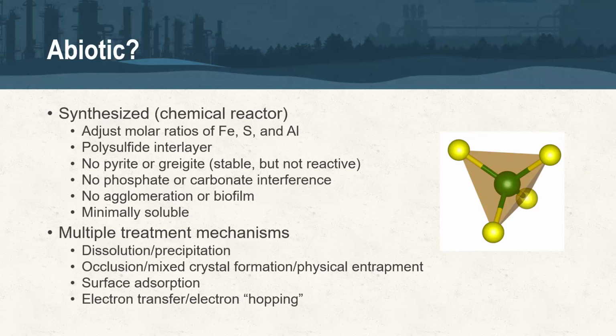But once you go through that process and you identify the most appropriate type of iron sulfide, you can work on loadings through your bench testing. And that's really where you start to look at the different treatment and removal mechanisms you're dealing with, right? Especially if you have a mixed metal site, it may not be as simple as using a 2-to-1 molar ratio of iron to sulfur. It could be completely flipped around. It might be 1-to-2.